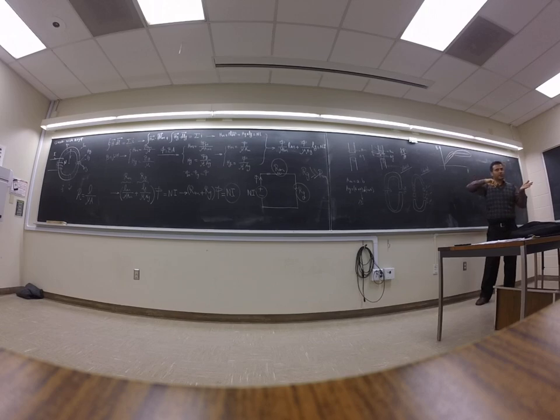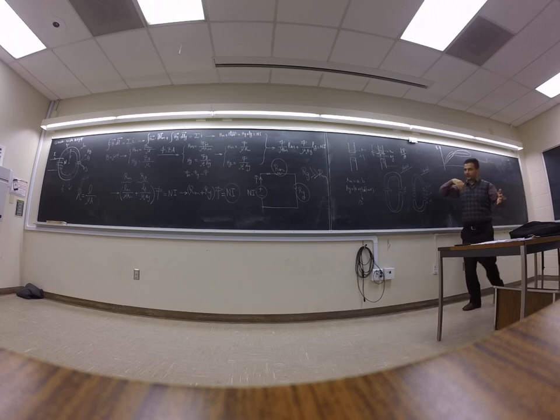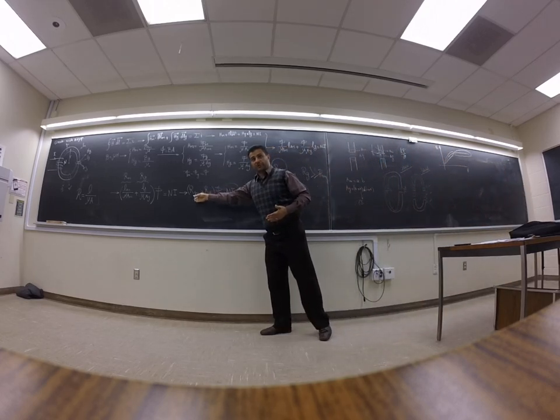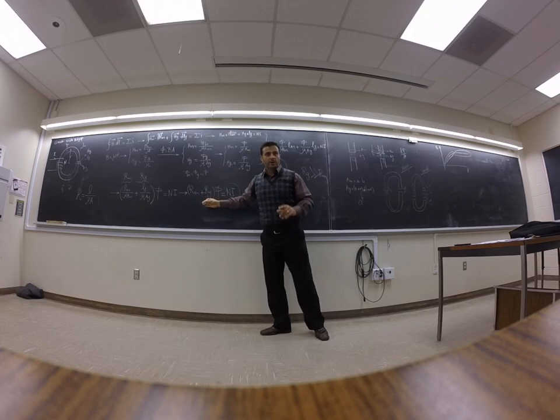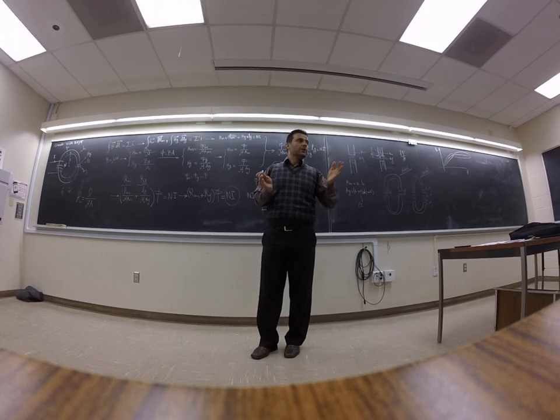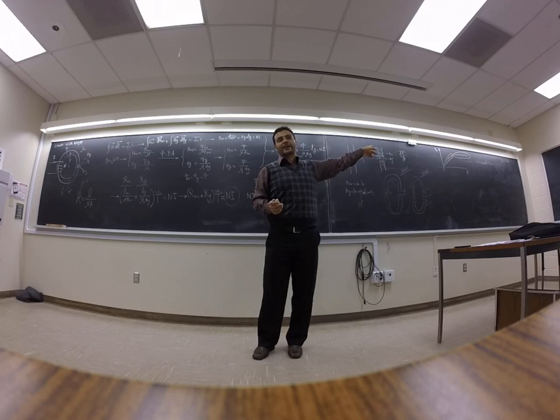You say 1.2 Tesla, let's go backward. How much resistance do I want in my circuit? So you say, okay, I select this type of core. This type of core is going to give me this much resistance. Still, I'm short this much. So I'm going to add a gap, a millimeter, half a millimeter, 2 millimeters, whatever. You calculate those things to make your circuit work. On that point you select it, and you think you have the best performance for the circuit.